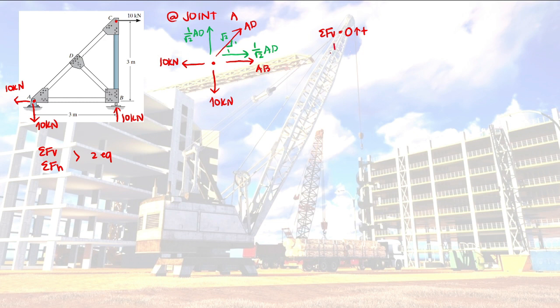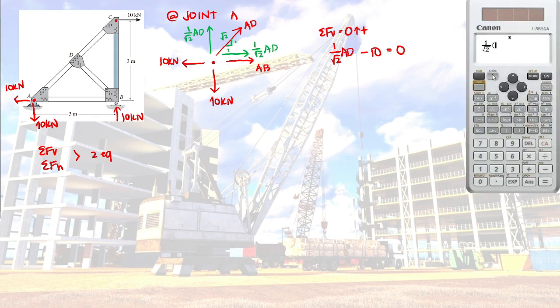So, that would be 1 divided by square root of 2, AD. Then, what else? You have negative 10 minus negative 10 because it is going downwards. So, this one is equal to 0. So our AD is equal to 14.14 kilonewton. So positive, therefore it is in tension.